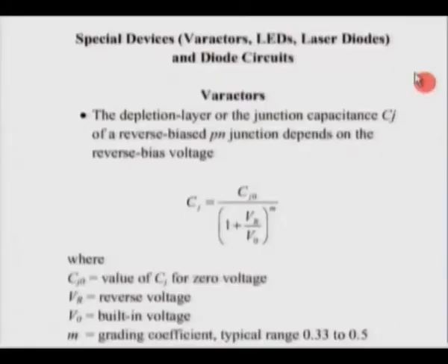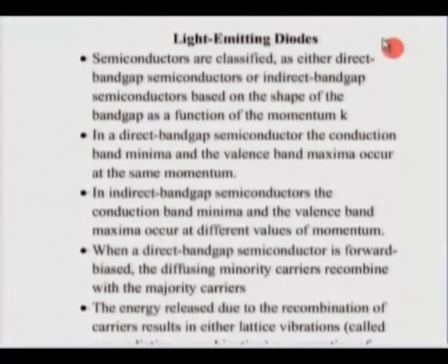We said that they are very useful not only in appliances and in radio, especially in fine tuning, and today we would find this very often. The principle there is that of a reverse bias PN junction, where the capacitance changes with the reverse bias voltage. Then we talked about light emitting diodes.